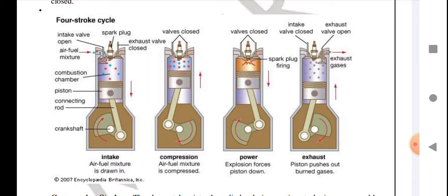So we use a piston ring, and the oil of the crankcase is not allowed to go to the cylinder area. So the purpose of the piston ring is to act like a seal which does not give any path to burnt gases or crank oil to reach the other side.